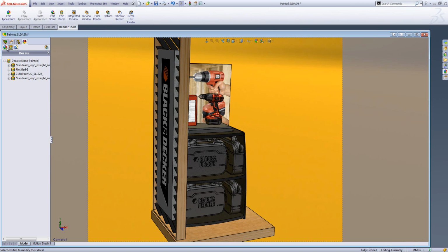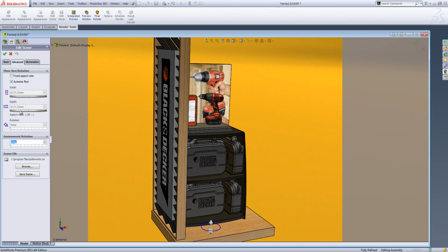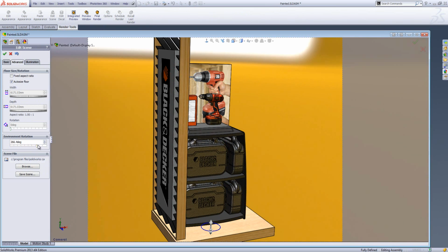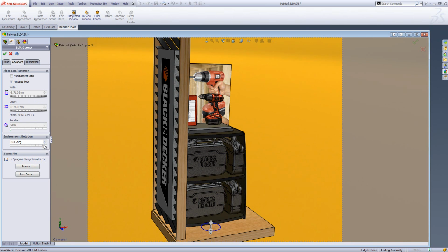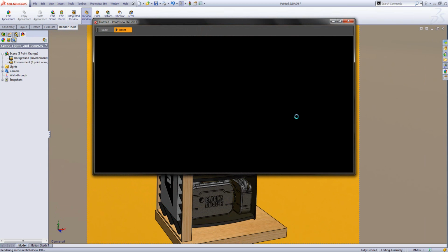We can then go ahead, and if we're looking to make simple changes to the lighting without actually adding new lights, we can edit the existing environment to just rotate it round. We can rotate this around the model, and you'll see the lighting on the model is actually changing as we're rotating it round. I'm going to rotate that round to around about there. Okay, just to make small adjustments to that. That should be about right. Once we've got it spot on, we can go ahead and do another preview render, and that should render out and give us a nice preview of the model.